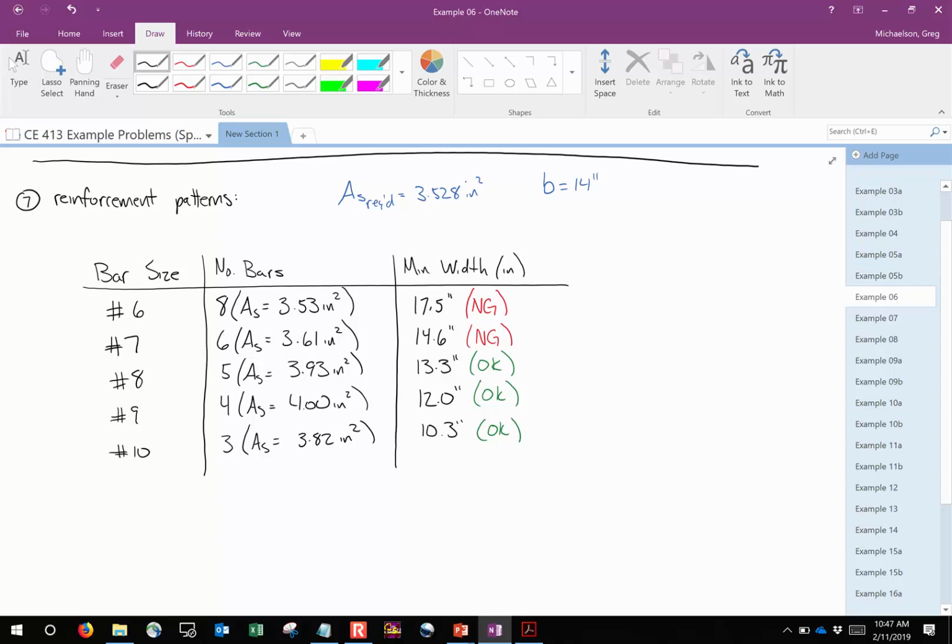Yes. That's what it's assuming: 1.5 inches of cover on each end, the stirrups, the bar diameters, and then a bar diameter or 1 inch between them. So that's what this lower table is computing for you. It's not terribly difficult. But yeah, sound good?